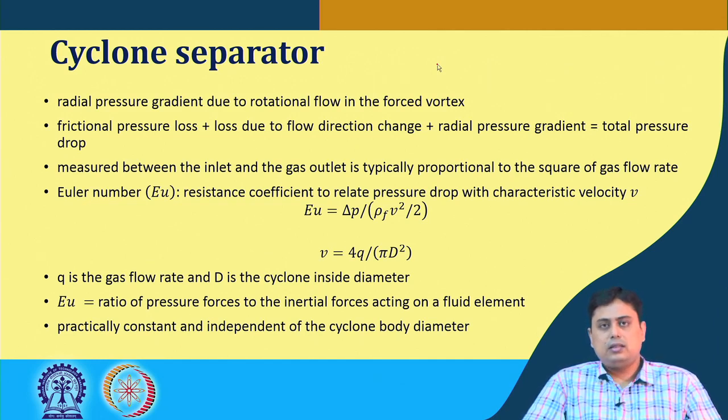All these combine to provide the total pressure drop, and it has been seen that it is typically proportional to the square of the gas flow rate. That means, as the gas flow rate increases, the pressure drop increases rapidly.